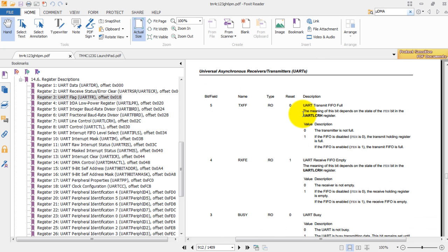So this tells you the state of the transmission. When its value changes to 0, that means that we are done transmitting any previous data. The data register is not full, or rather the transmitter is not full. So that means we can fill it up with some data.